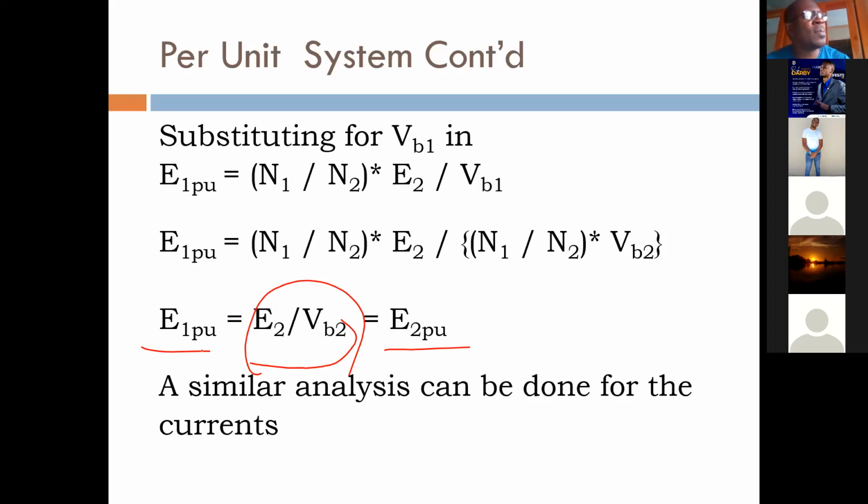Why am I telling you all of this? Because when you purchase that transformer and you're going to install it in a network and do your calculations, the manufacturer is not making the transformer just for your network. So he's going to give you the ratings of the transformer, whether the reactance, the MVA rating, you name it, based on the unit itself.